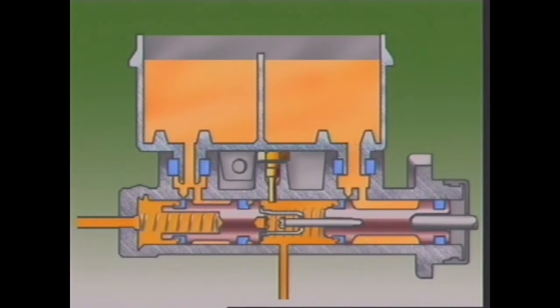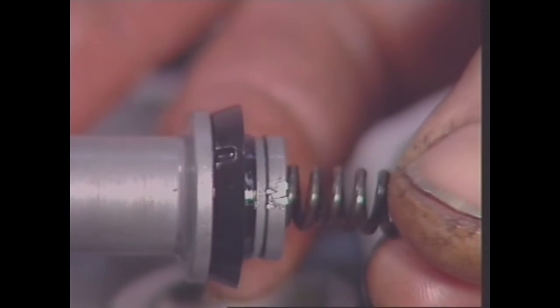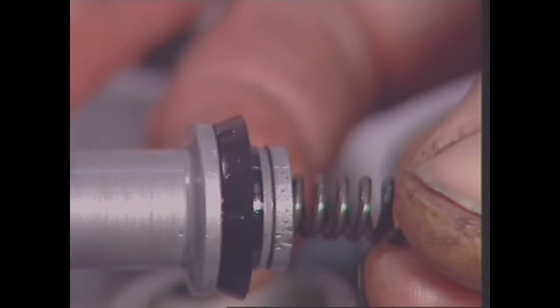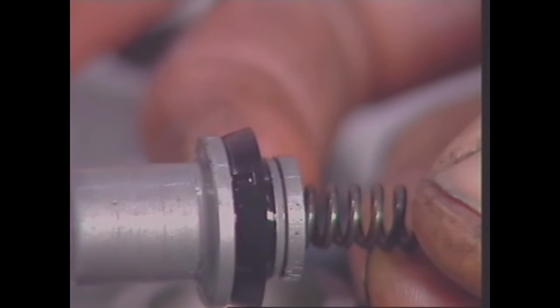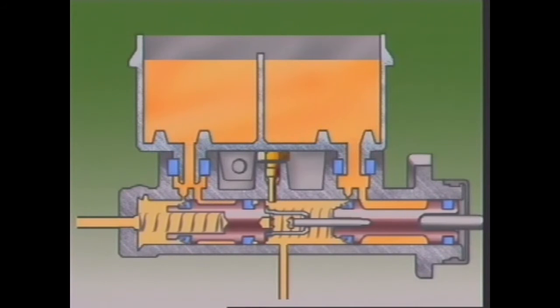The tandem master cylinder can have problems with a low pressure area developing when the piston returns quickly, but the fluid lags. The tandem master cylinder overcomes this by using grooves in the side of the primary cup. These grooves allow fluid to flow from the inlet port into the low pressure area.